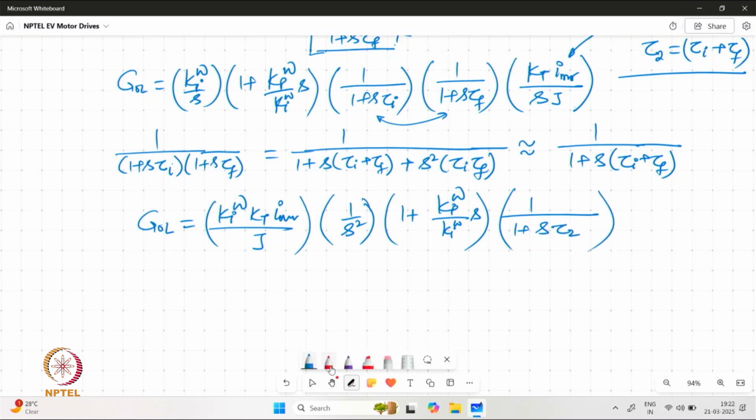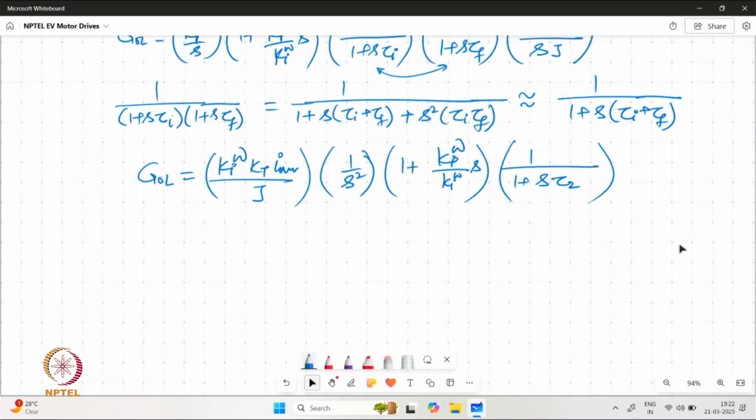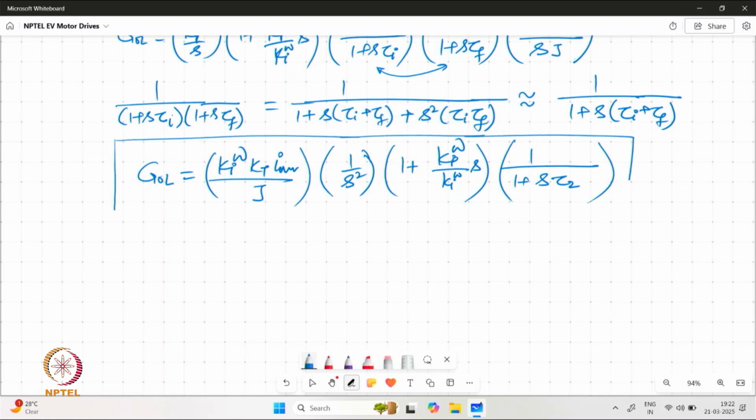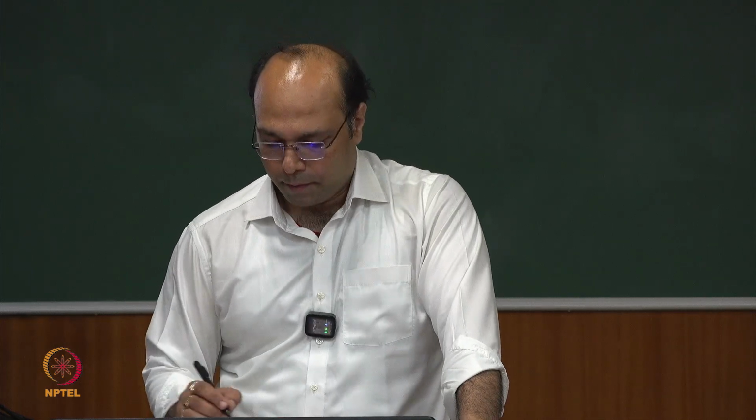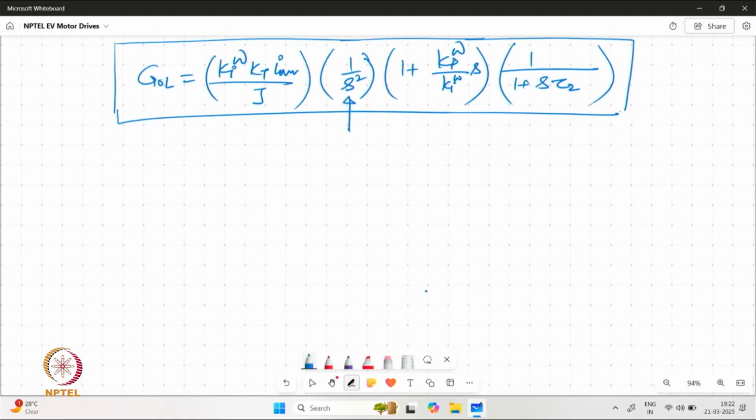is written over here. So now, comparing with the previous designs what we have done during this course, once again the system is found to be unstable on account of this double pole located at the origin. So we are going to have unstable system if we are only going to approach the design by having pole zero cancellation. So we need to have a different method, and we can go for once again the symmetric optimum method